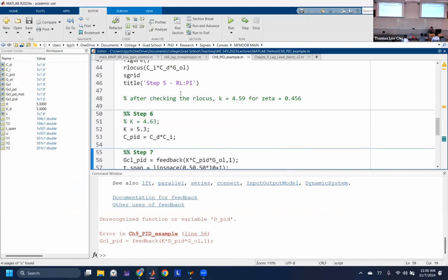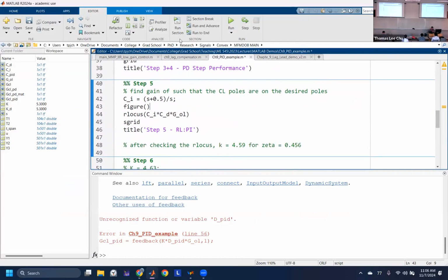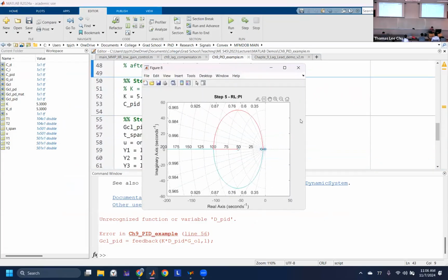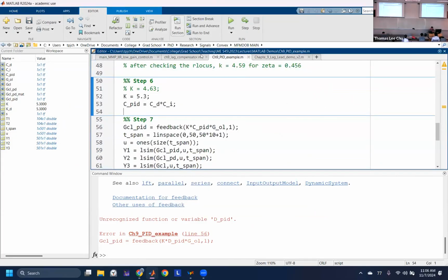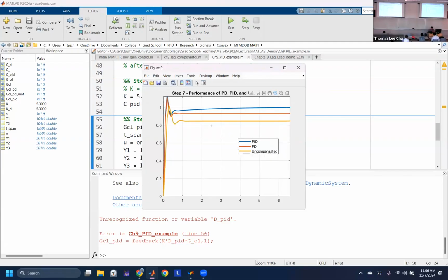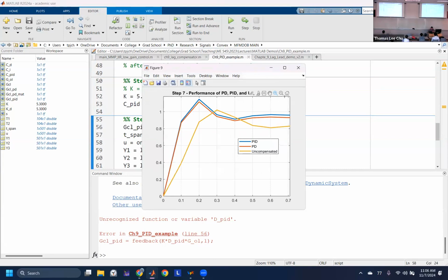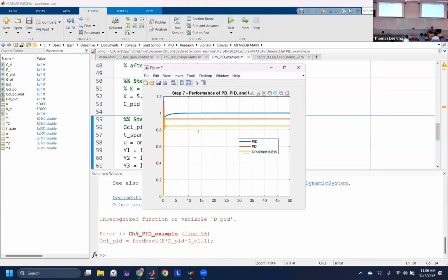All right. So now, if I want that really slow transient response time to move a little faster, I can move my pole location or I can move my zero to be further away from the origin. So I'm going to choose zero point 0.5 now. And if I were to run it again, now you can see this convergence is a lot faster. So it converges at 5 seconds compared to, I think it was like 20 seconds earlier. Peak time is still similar, and now we're just converging a lot faster.